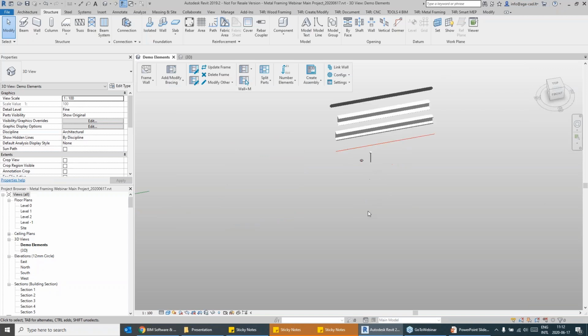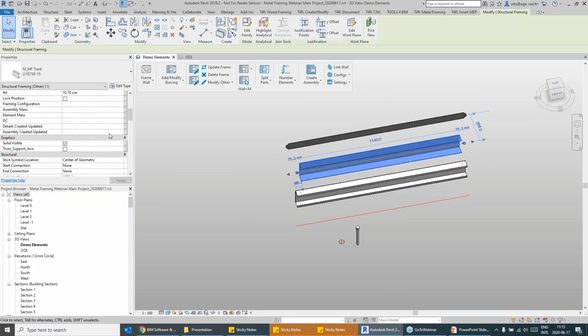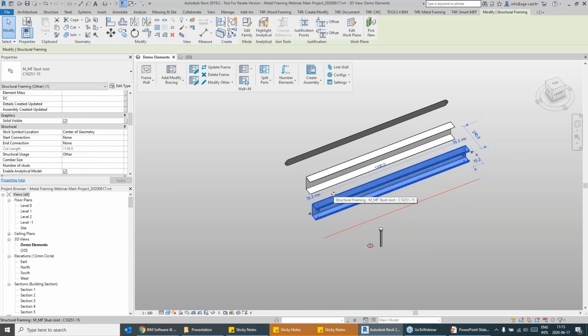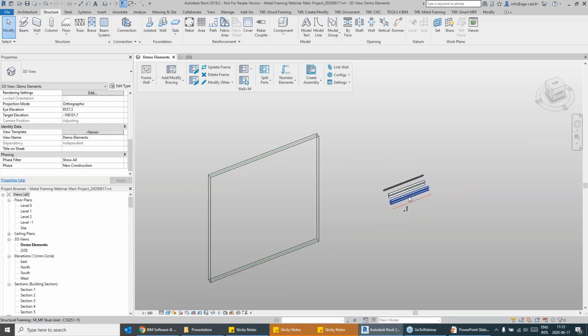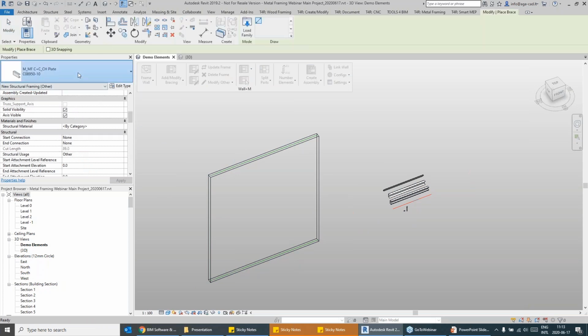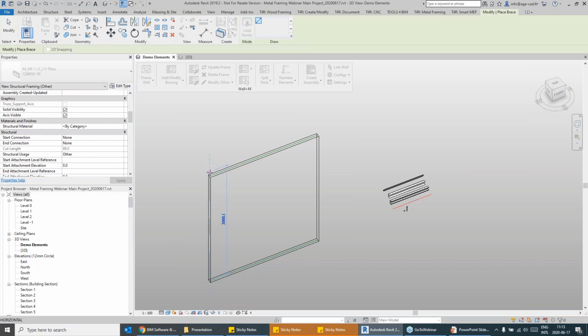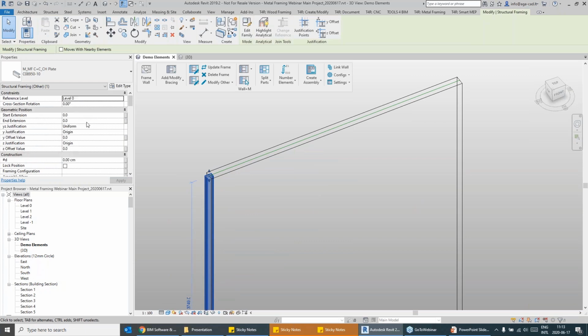Imagine I have those profiles. Those are just regular Revit families. Actually, not very regular. We have added some parameters to them so they can be more flexible and more efficient and can work automatically in different ways. And imagine you need to apply those profiles to that wall. If you do it manually, that would take you some time. You need firstly to choose the correct profile, then you need to draw it on the wall, and maybe you need to rotate it.